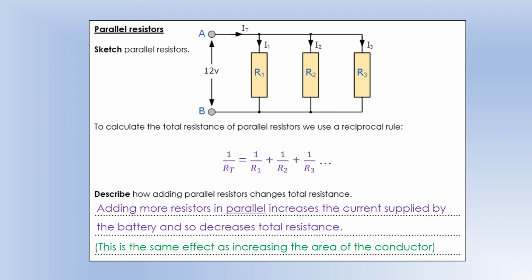So in the previous video, I said that voltmeters have infinite resistance, and I said one of the reasons for that is it has no effect on the circuit resistance. So remember, voltmeters are connected in parallel. So if we imagine our R3 resistor here is actually a voltmeter, if we put R3 equals infinite into the expression, 1 divided by infinite is 0.